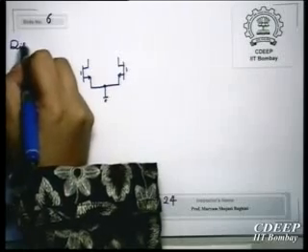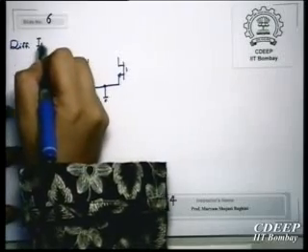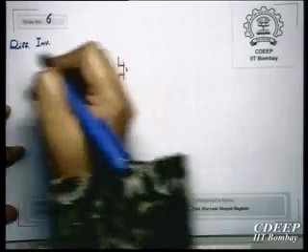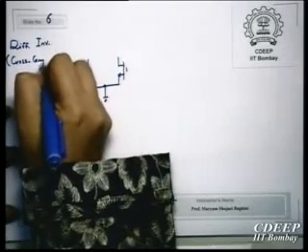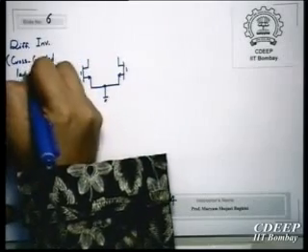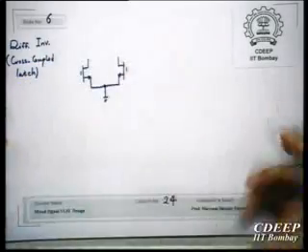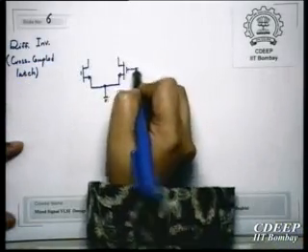So this is a differential inverter. Actually, it's a cross-coupled latch, right? Because till now, whatever delay element we are talking about, all were simple inverter or current starved inverter with single-ended.